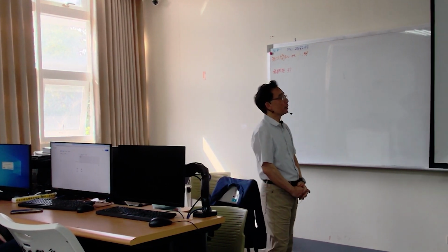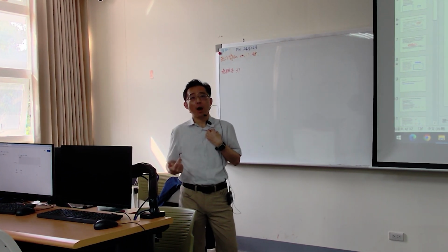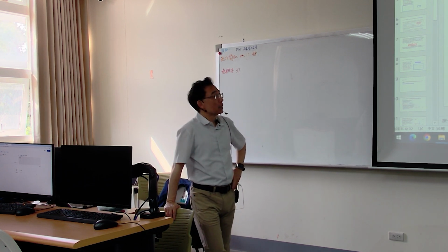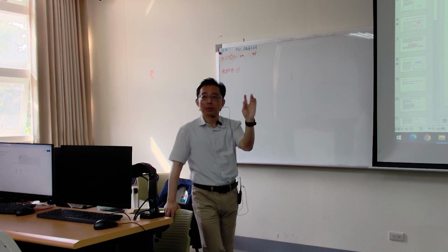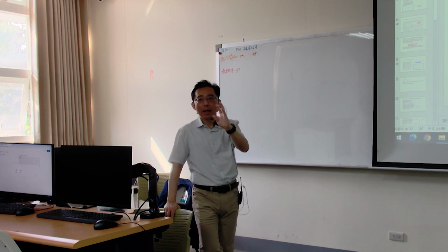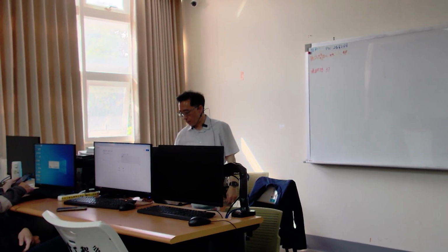In that case, I use the same diagram to describe a little bit. If I want to rotate with a fixed frame, so when I rotate with y, I have a new z1, right? But I want to rotate with z0. So how can we do? Then we need to reverse back to the original coordinate, then rotate with the z-axis, then come back to the axis already rotated with y. This is a long description, so let's see from the formula.